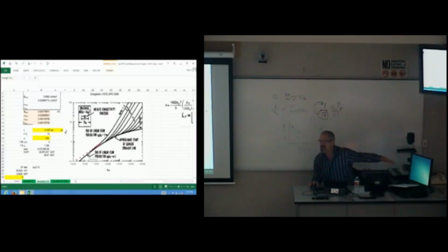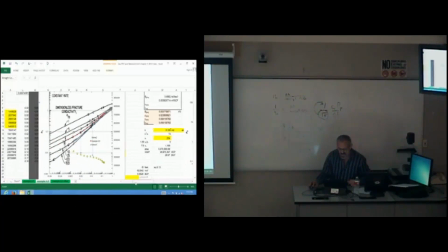As you decrease the conductivity of your vertical frac, you increase the amount of time that you're in bilinear flow. And all we can say quantitatively is that we're going to be above that line, just like the Bennett type curve shows us. But that's the end of linear flow for infinite conductivity, where this sentence and this arrow is, this last X, which I've just about completely wiped out.